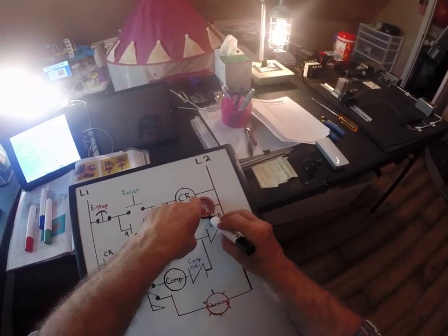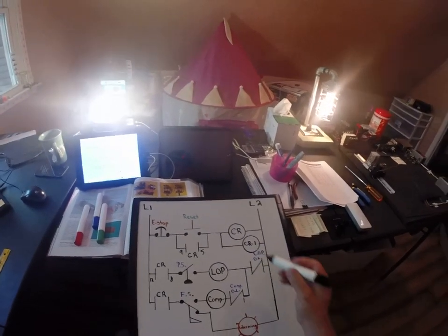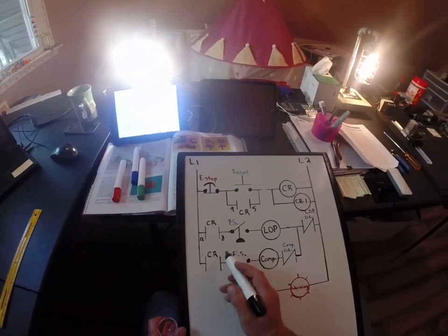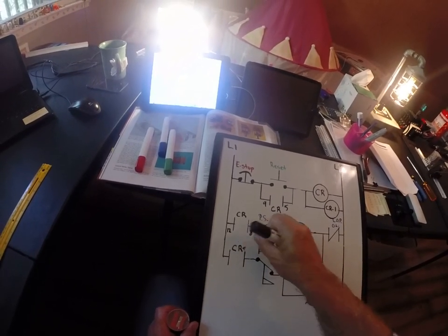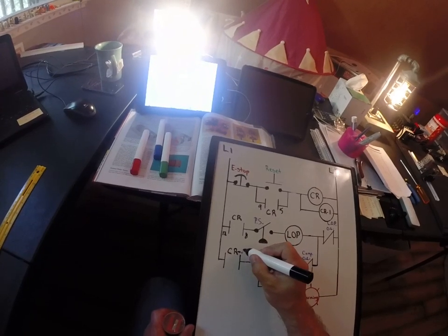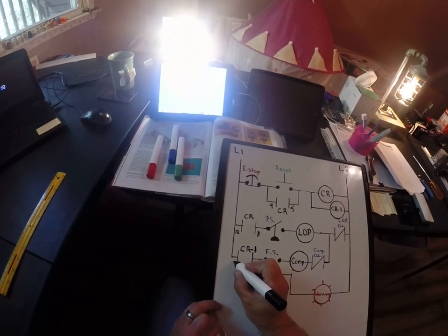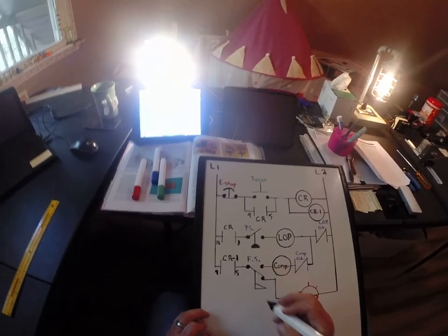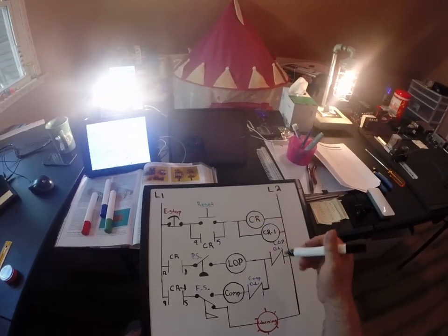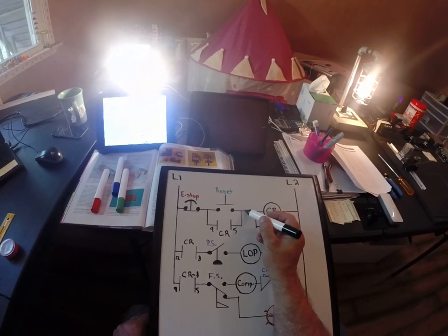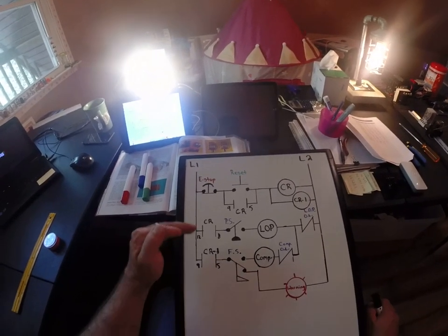Try to draw this in here, just sneak it in there. We're going to call this CR1. So when CR gets energized, it's also going to energize CR1, but we got to rename this one. We're going to rename this one CR1. That allows me to use those contacts on that relay, and I could start over again, so I can put a 9 and a 5 here. That took care of that problem of not having enough open contacts on 1 relay. So how do we fix that? We add a relay in parallel with the one that was already there, and we rename that contact. So you can kind of see how that works.